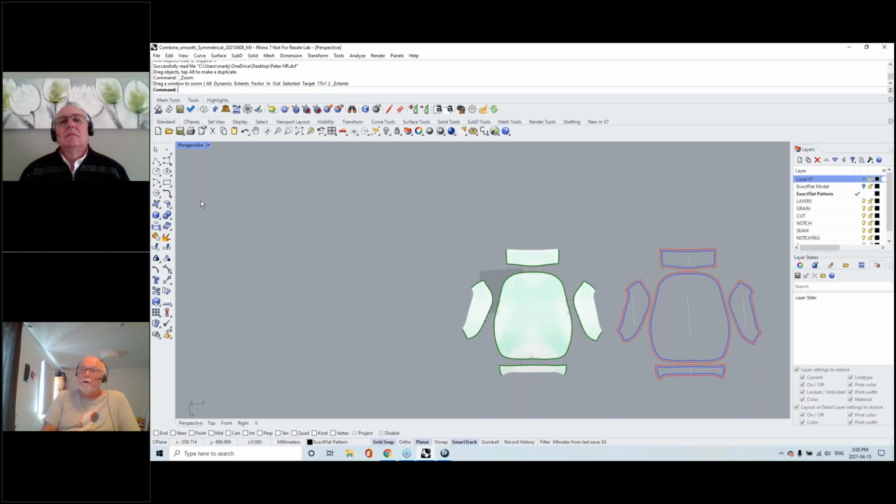And if you're describing a large mining machine, you can certainly drop your mesh resolution just to save memory and file size, but you would have to apply targets along the object as you scan.